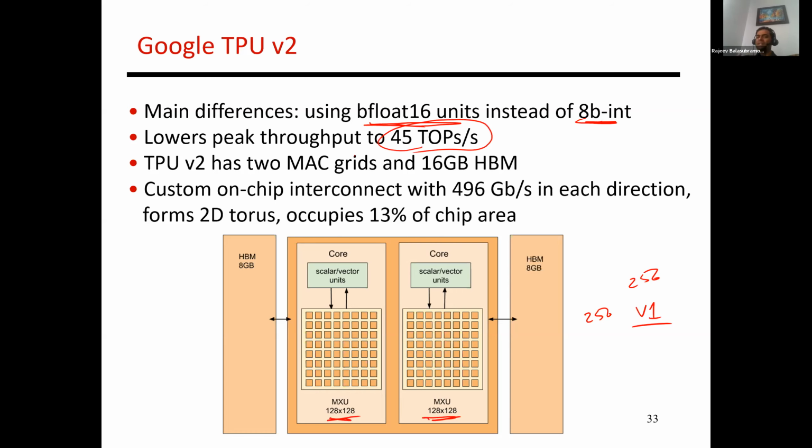So it almost seems like it's a more inferior design, but it's not. This is a much better design, more area, much better memory interface. It's using HBM for high bandwidth memory. But because each ALU is doing a different operation, it seems like it's got lower throughput. But in most regards, this is a better chip than the V1.